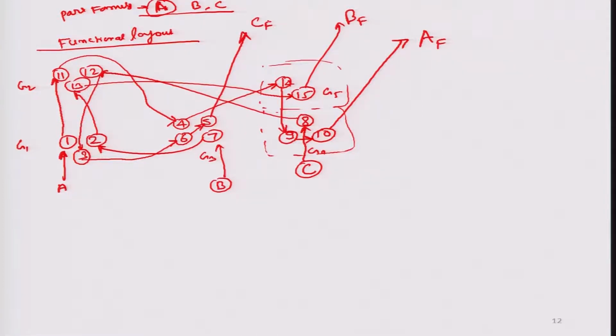So you can see that all parts are moved in a very complicated manner. A very precise design is required, and it takes a lot of floor space. Suppose that for part family C, after finishing the work on machine 8, it will move to machine 12 in group 2. The time required to reach from 8 to 12 is very high. Also, you will have to design the pathway for each part family to transport from one machine to another machine.